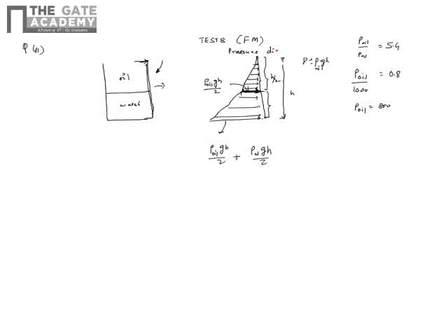One important concept in hydrostatic force calculation is that the volume of the pressure diagram gives the magnitude of the hydrostatic force, and that is what we want.